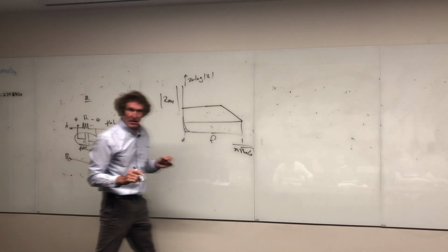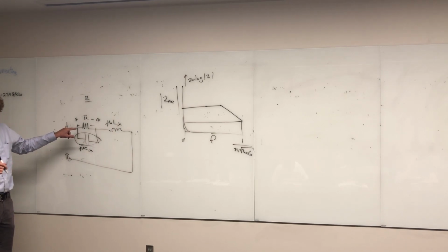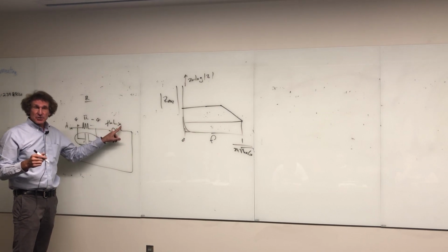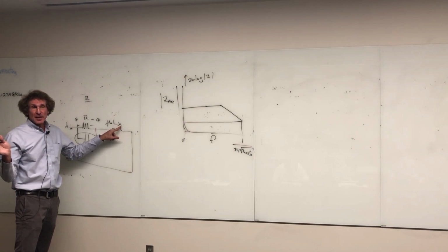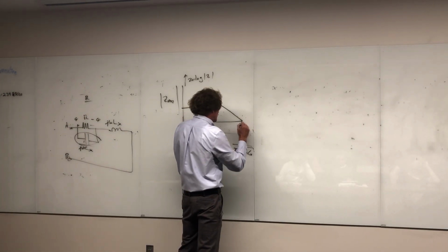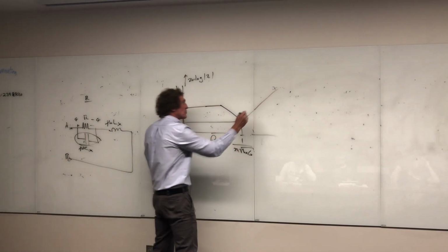Now here's the crazy thing about what I'm doing here. We know that the resistance of this wire is changing once it gets into the range where skin depth becomes a problem. We also know because of that, the inductance value is changing too as you get to higher and higher frequencies. So this first order model is just that, a first order model. And this is what you'll see on a scope basically, not exactly. If you look at the Bode plot of this, that's the resonant frequency. Then from here on, it's going to go up at 20 dB per decade.